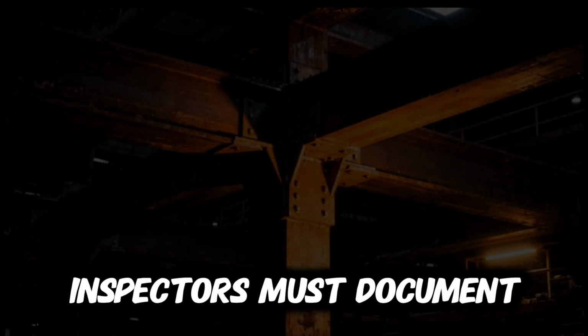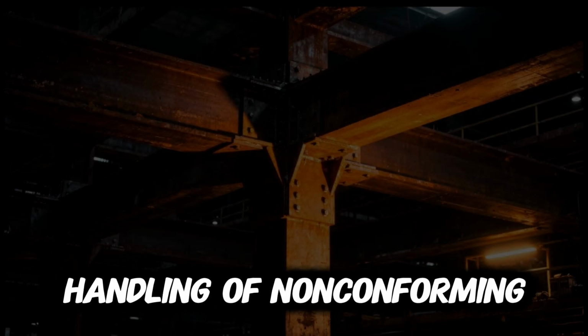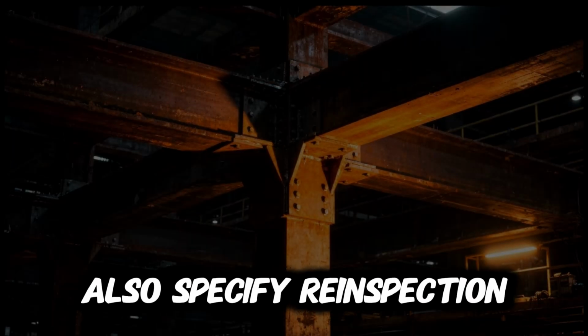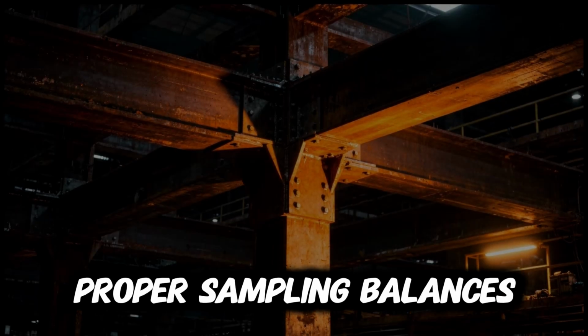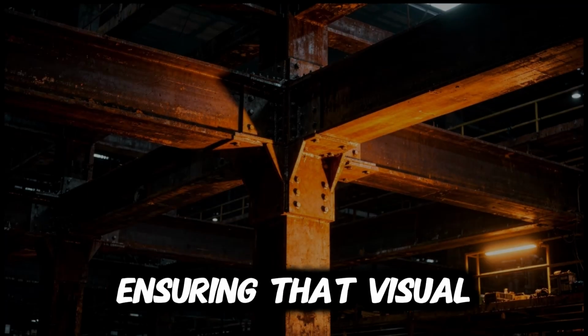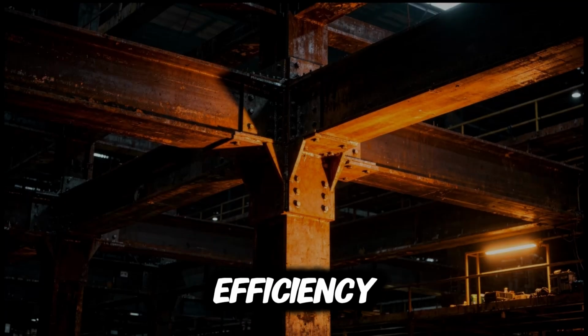Inspectors must document the sampling rationale, selection method, and handling of non-conforming units. Batch evaluation protocols also specify re-inspection procedures for rejected lots and escalation paths when defect trends emerge. Proper sampling balances inspection effort with risk management, ensuring that visual testing supports both quality control and production efficiency.